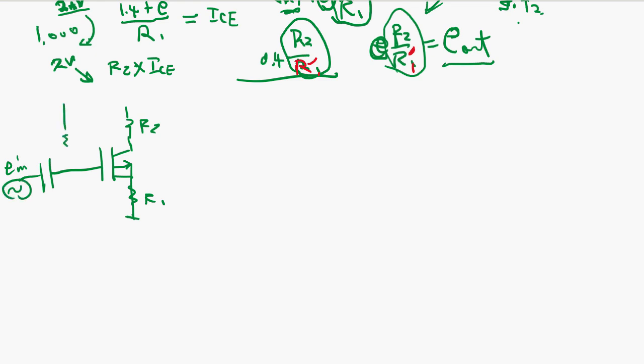You have to set the operating point of the transistor by this R4 and R3. Usually you use a high resistor here, so this signal is going to translate to the gate voltage very well, and this drain and source,